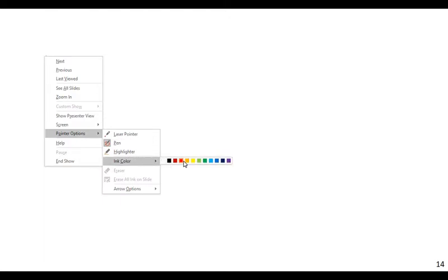Does anyone know one of the advantages of not having the door rotate about its centroid? Well, there's one disadvantage: you actually induce a vertical moment on the supports. So you need stronger hinges to hold a door like that than you'd otherwise need with, say, just a simple pole going down the middle or a socket joint on the top and the bottom, because you do have to resist moments. But there is actually a great benefit to having the hinge on one side: you reduce the force required to open the door, because you're effectively doubling your moment arm length.